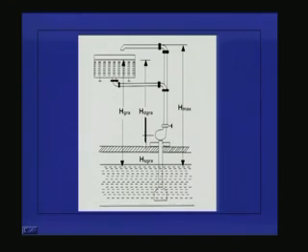If the pressure is below the vapor pressure of water, then vaporization takes place. That is what we call cavitation, and cavitation means the bubbling will start occurring, and when these bubbles get transported through the pumping system, they could reach regions where the pressure could be very high. In such a situation these bubbles will collapse. This is what we call pitting. If cavitation occurs in the operation of any pump, the life of the pump can come down very significantly. So, cavitation should be avoided like a plague.